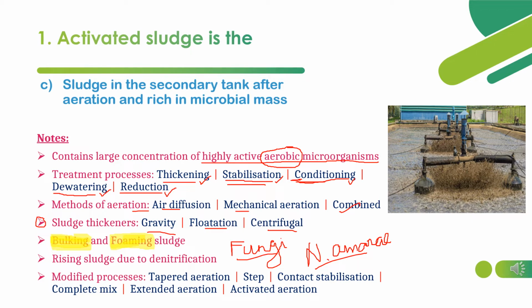So for foaming sludge, foam removal is also a logical and beneficial control measure, since these Nocardia filaments are usually concentrated in foam compared to mixed liquor. So when foam is formed, this will be beneficial for control measures.